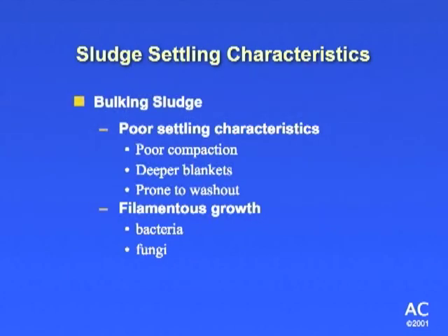Young sludge is one that can cause it too, because it won't settle as well. Young and restless, they'll say. But typically it's filamentous growth. What you want to do is stop the conditions that are causing the filamentous growth from occurring.